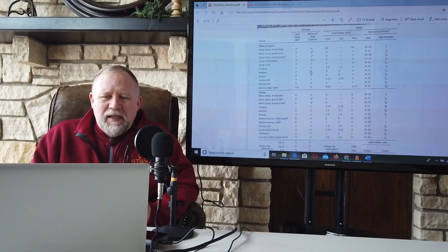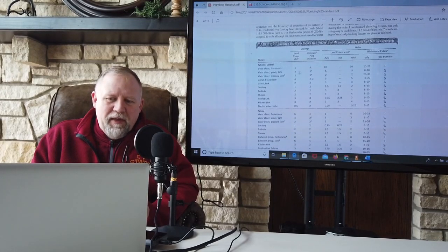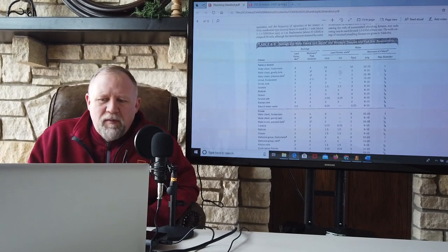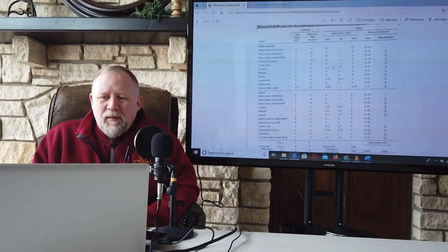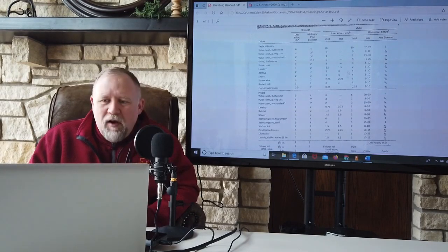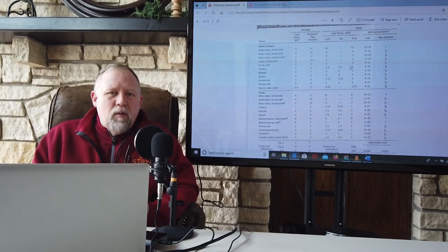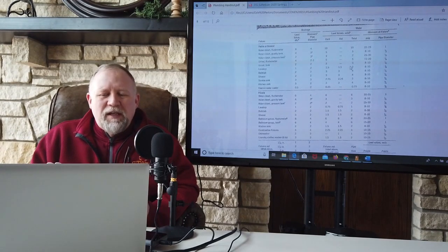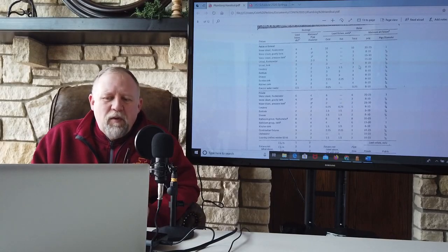And then we go down to this table, table 8.6. Now, instead of using the drainage column on the left, we're going to be using the water column kind of in the middle. So see where it says load value and then water supply fixture units? That is the one that we're going to be using. Only use the total column, the third column under water supply fixture units. We do not need to do the hot water separately from the cold water.